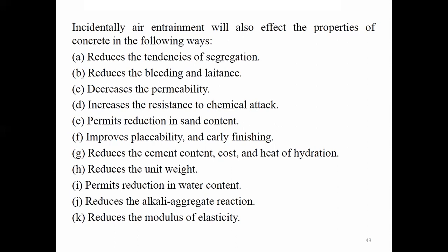It is not as dense as the conventional concrete. So these are all the reasons for the reduction in the sand content, water content, unit weight, cement content, and all. Whenever the cement content is reduced, what happens? Obviously, the heat of hydration will be reduced. That is also very clear.